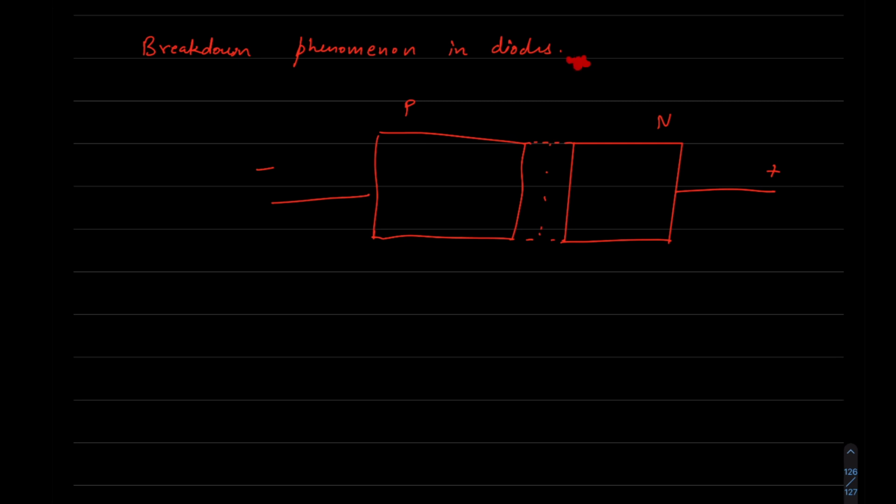If the current is limited, the diode still can function under breakdown voltages, but we need to control the current. This is very similar to breakdown in insulators, as you may know. If we have voltages high enough, we can ionize the air and then we have these arcs. So the breakdown voltage there is the voltage at which the material conducts uncontrollably.